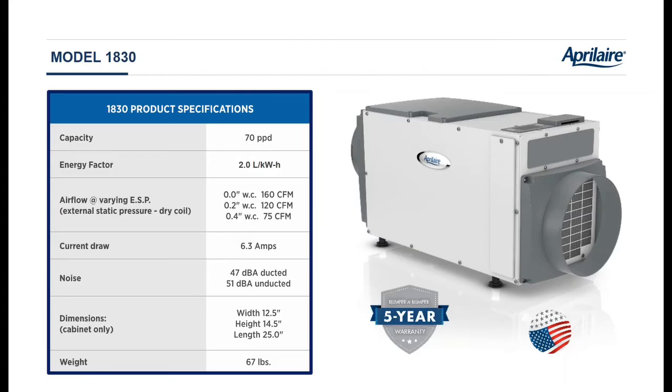It hits set point, it shuts off. Then you have to wait for that humidity to migrate back in for it to then run. So you get lots of downtime. By moving as much air as we're moving, you're constantly pushing the dry air away and pulling more humid air in so it can keep dehumidifying the space.